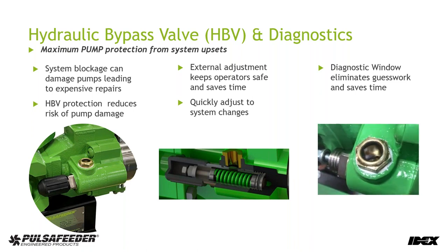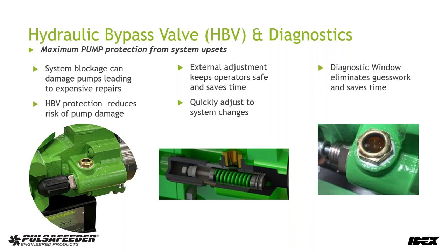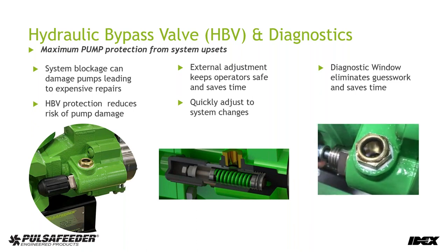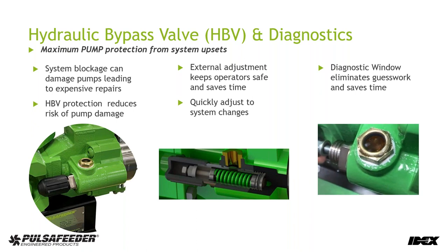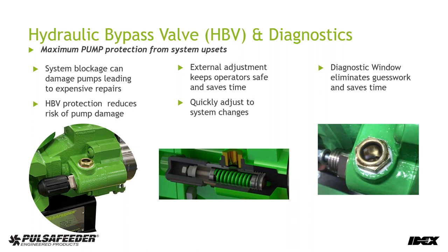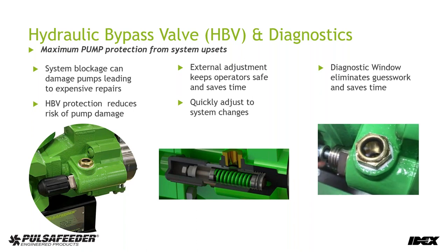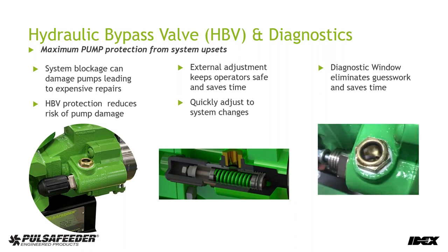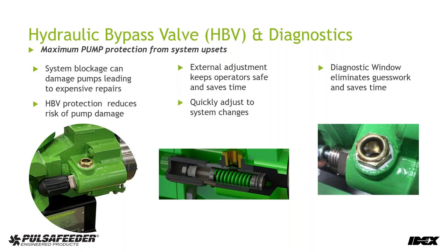So when you're troubleshooting, if you have a system problem, this gives you a real quick indication of whether or not this pump is the problem or I need to look someplace else. So it saves you time in troubleshooting and evaluating system status. So that diagnostic window is a key element that eliminates guesswork and saves you time.